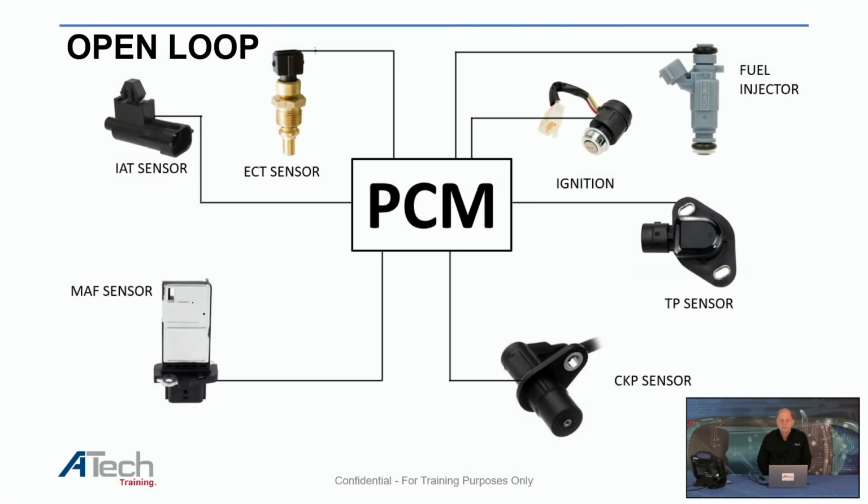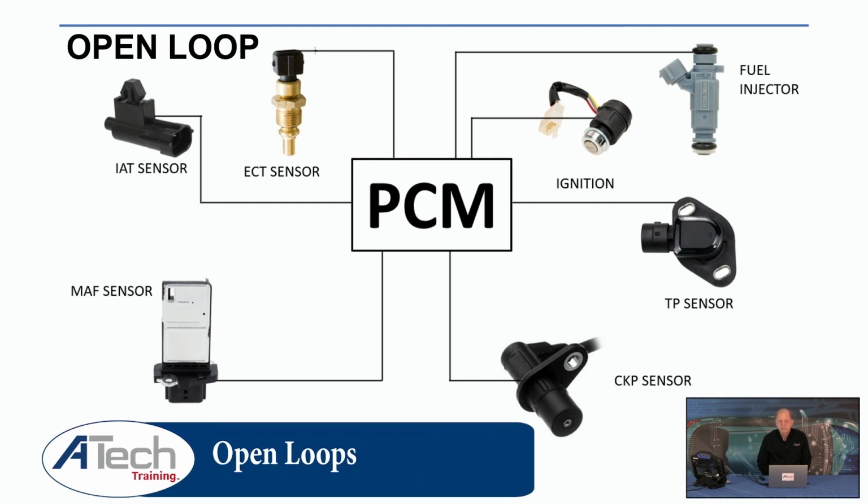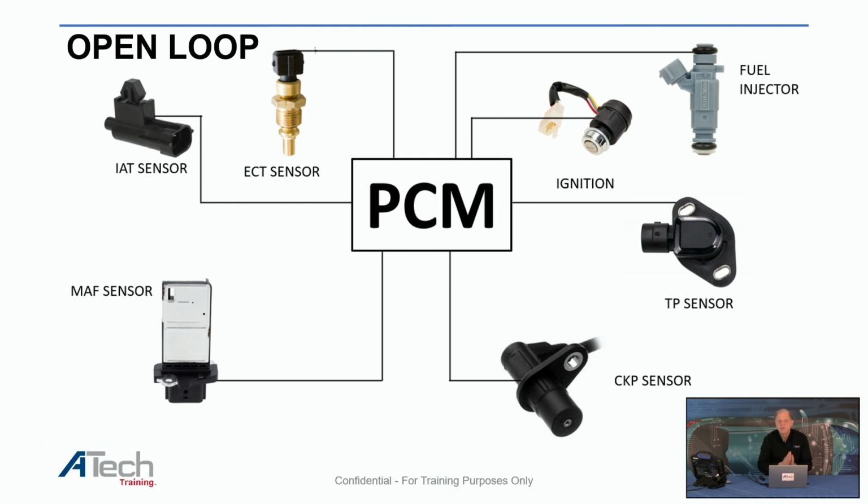This is open loop. We're looking at it, but the information I've given you so far might change your perspective of what you should be looking at. First of all, I can have a MAP sensor. This one just shows a MAP. I'm not telling you what company I got this from, but it would have this data up here. What else is missing at this point in open loop? The other thing to keep in mind is we have long-term fuel trim that's related in open loop.